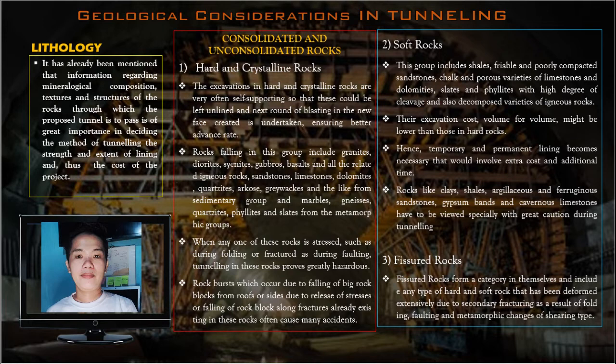In considering the lithology of the area, the consolidated and unconsolidated rocks should be looked upon too. These involve hard and crystalline rocks, soft rocks, and fissured rocks. The excavation in hard and crystalline rocks is very often self-supporting, so that these could be left unlined. A next round of blasting in the new phase created is undertaken, ensuring better advance rate.